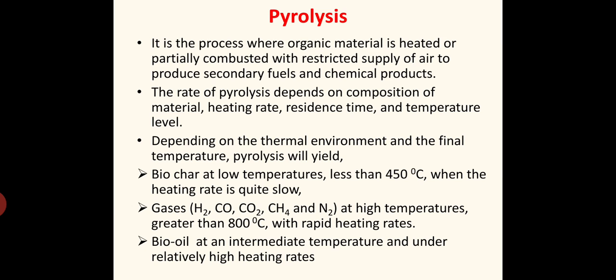It is the process where organic material is heated or partially combusted with restricted supply of air to produce secondary fuels or chemical products. The rate of pyrolysis depends on the composition of the material, heating rate, residence time and temperature level. Depending on thermal environment and the final temperature, pyrolysis will yield different products. These are the set of conditions based on which what we will get is discussed here.